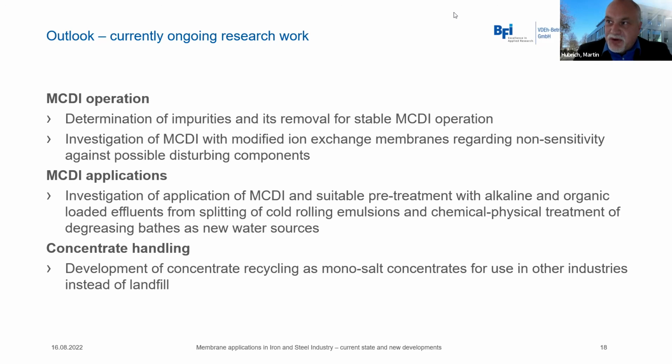So during the operational process, when you are removing the ions, you are not getting into an area where you have an oversaturated solution. But when you are regenerating your modules, then you release ions, you have a comparably low water flow, and then you are in danger of having precipitation residues.